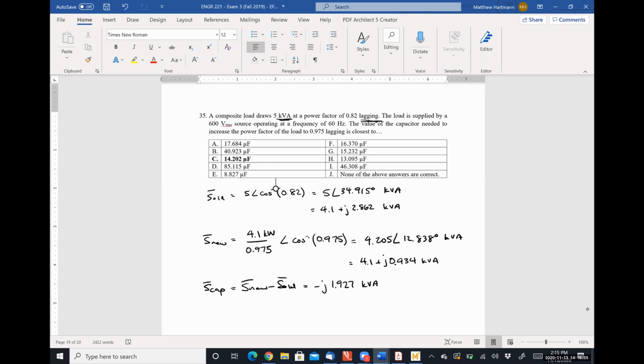I don't understand your question. They do. So if we had an inductor, you would not put an inductor in to do power factor correction unless you had a capacitive load, and those in practice pretty much don't exist. So in an industrial setting, you are going to have inductive loads because you're using inductive motors in your HVAC units.